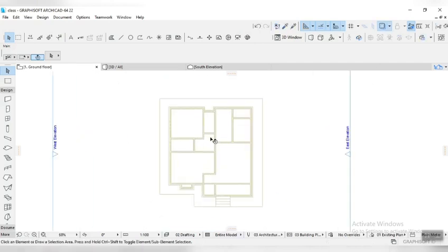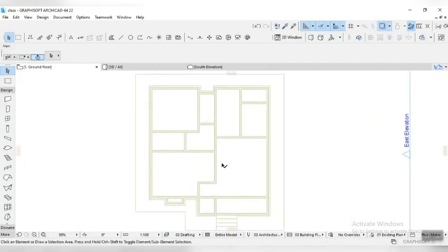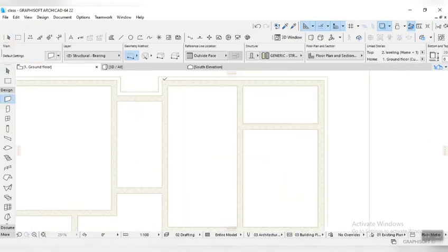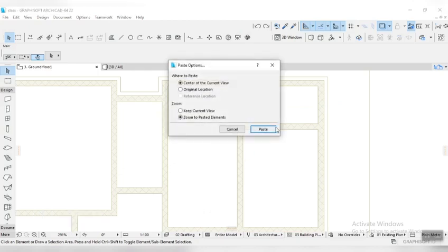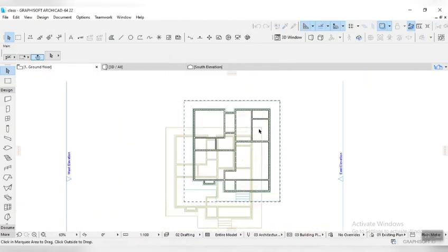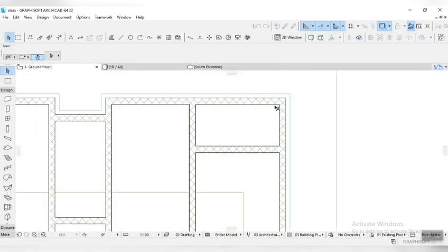Now you can see that everything on the ground level is displaying. If you didn't copy, you could just use your wall tools and recreate all these objects like this. Let me show you something. You come here, you go to the inside layout, and you put it all through. But me, I don't like it. I like using my copy item, so everything is going to match. So I'm going to paste, then I'll move it to fit my desired position.